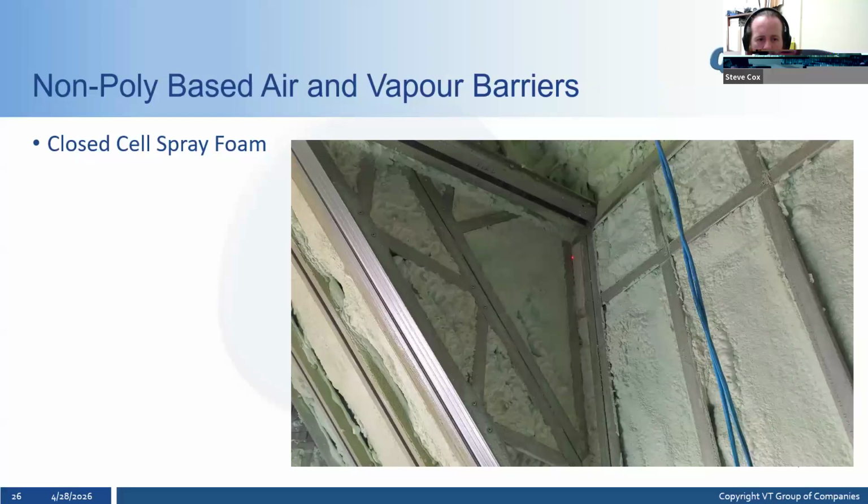If we have a failure with that, then the condensation can get in there and we have a big problem. Especially where there's an unvented attic that's treated with spray foam, but every building that has spray foam, in my opinion, should at the very least be treated with a blower door test to find problems, let alone to find the ACH and the NLR, just to find the problems so that it doesn't cause warranty work later on for the builder or the homeowner.